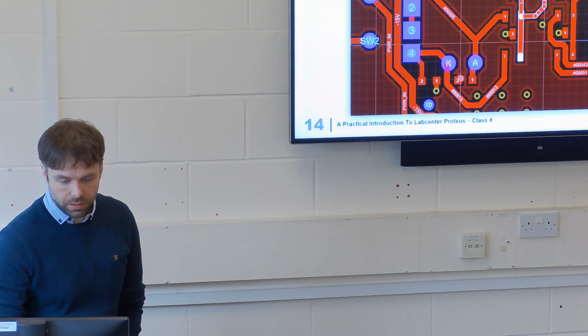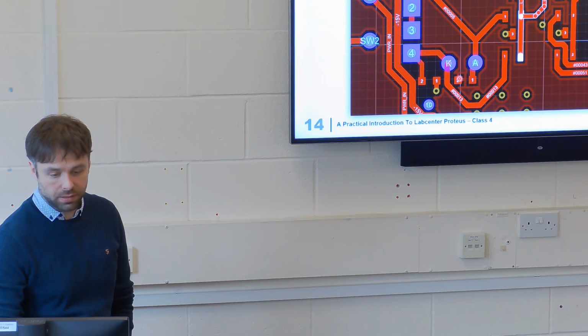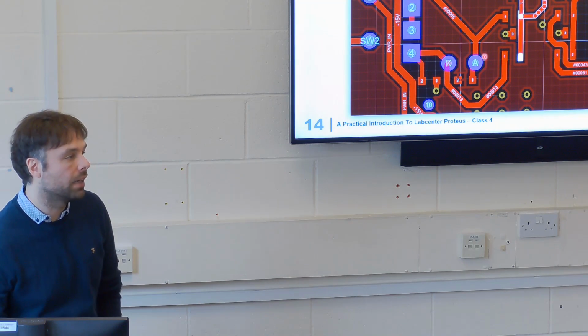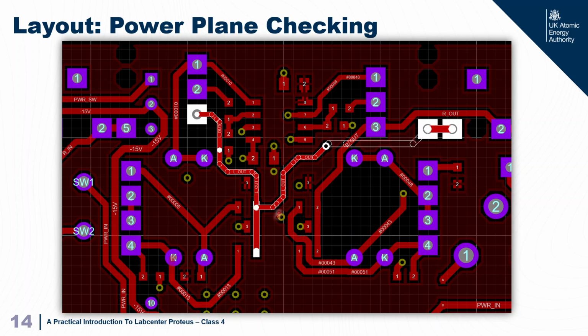So, with high speed signals, immediate current draw, this trace meanders around, let's call it goes around the woods. It has to, you've forced the current in a way that it might not want to go. So, for example, you're going through that trace, that's blocked, can't get through there, can't get in here, comes around here, okay, then now it can connect to this. But what if you want that to connect to like this or even these over here? You'd have to go all the way around.